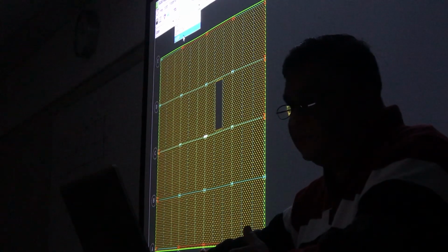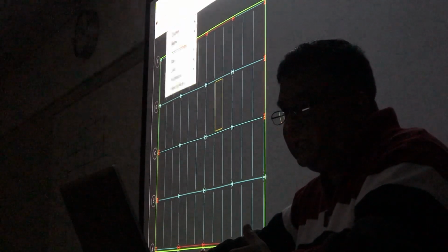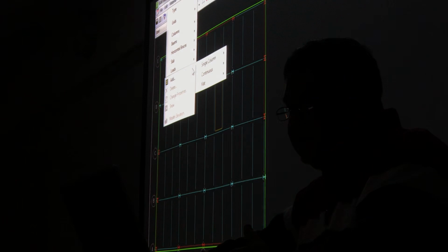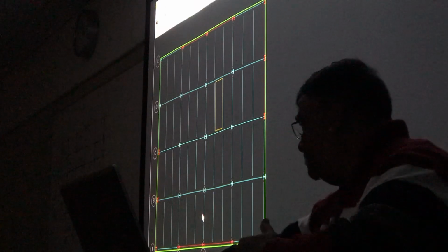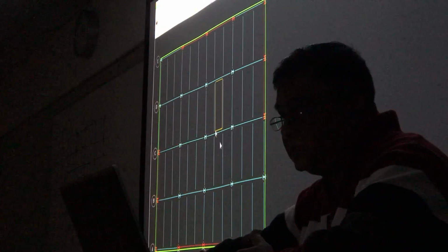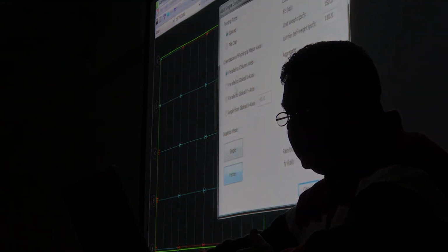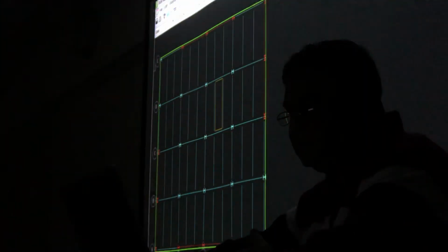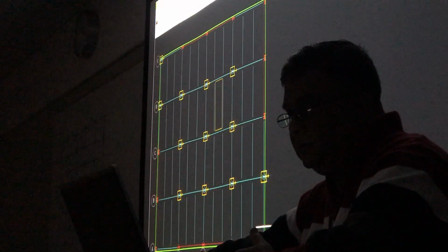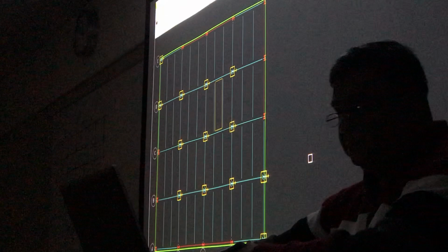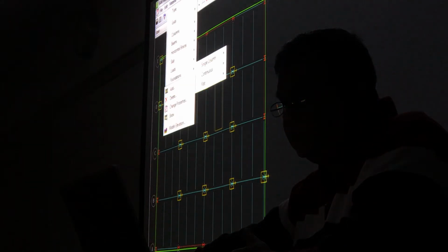And also I am on the first floor. I don't need to change the loading, but the only thing that I need to add is the foundations, which is our next step. Foundations will have individual column foundations and also moment frames and brace frames. I need moment frames and brace frames to be continuous foundations. So layout, foundations, individual column footing, add, and I think I will not change anything. These are my columns which need individual column foundation, and I will need individual continuous foundation.